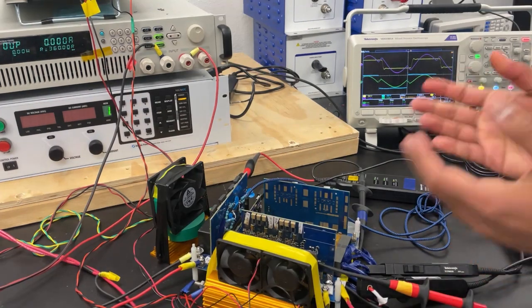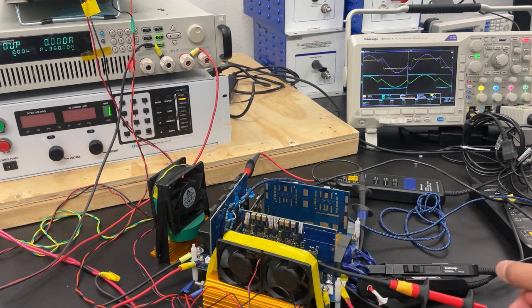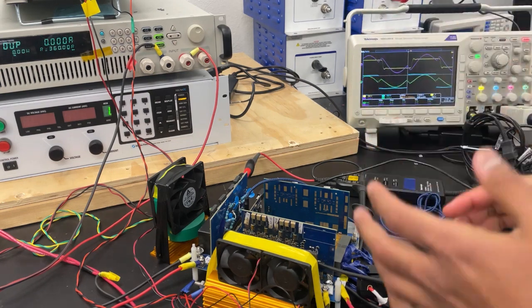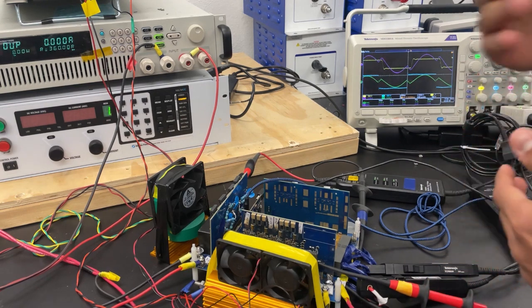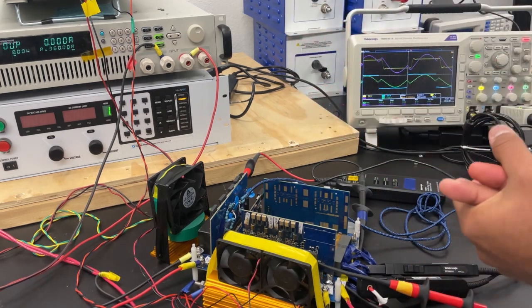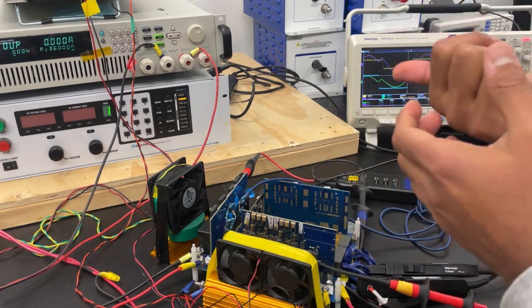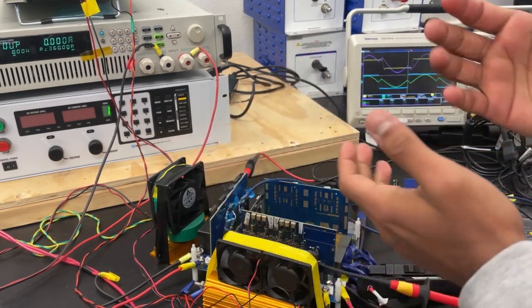Hello. I've turned off the fan so that we can discuss the results. As you can see, this is the waveform which I obtained. Right now, I'm measuring the switch node voltages of the primary bridge and the secondary bridge, and I'm transferring power from the primary to the secondary. I'm also measuring the current going out of the primary side full bridge and the current coming into the secondary side full bridge, with that orientation.